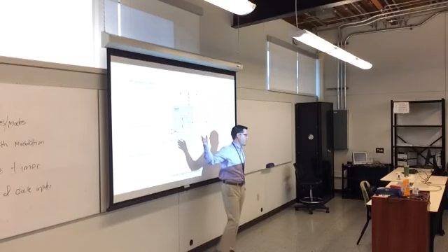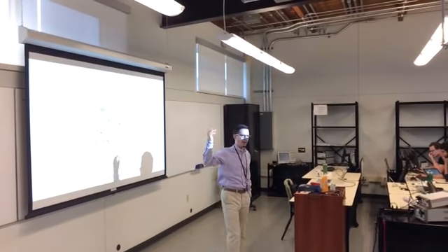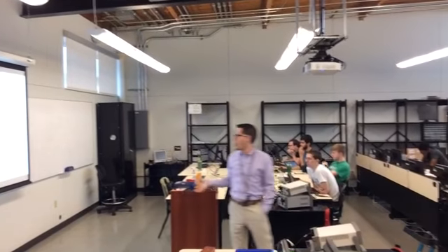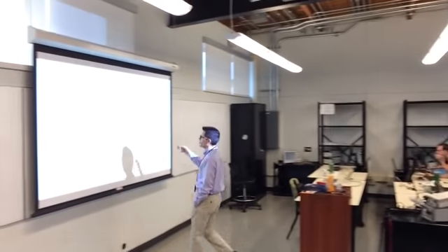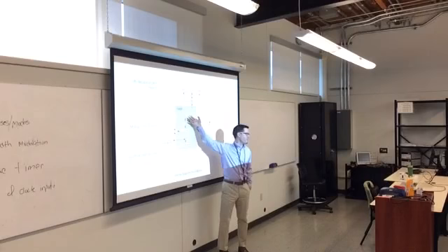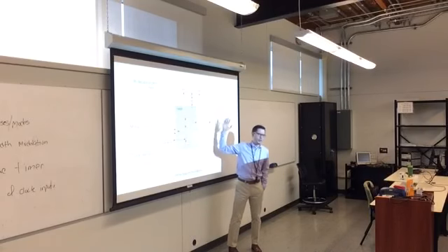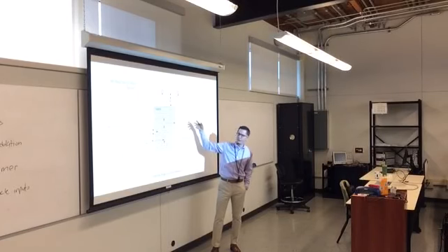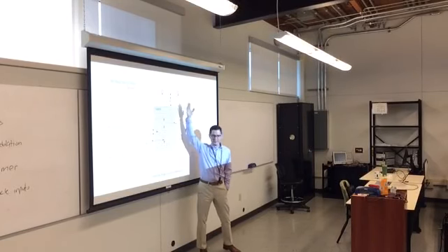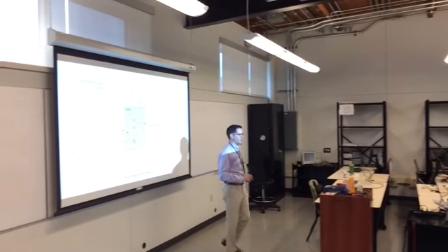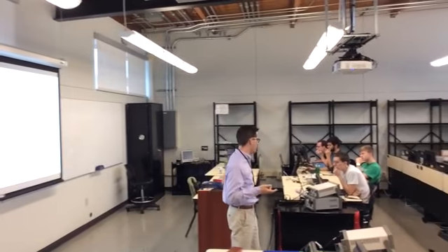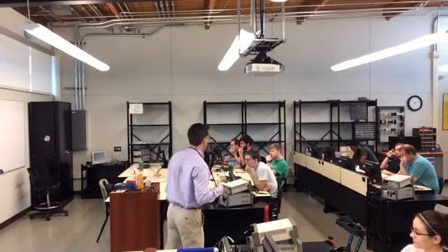Whether the input signal is high or low, maybe it counts up, maybe it counts down. Overall, that counter gets compared to some value, and when it matches, it outputs another signal, which can go to another peripheral, to a GPIO pin, or cause some sort of interrupt. So there's always going to be a clock coming in, there's always something you're comparing to, and depending on the mode you're in, you're either going up or down.